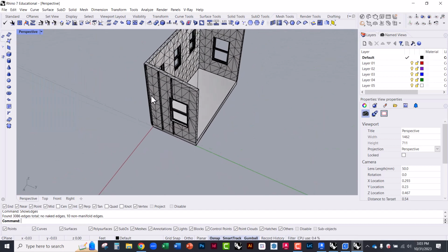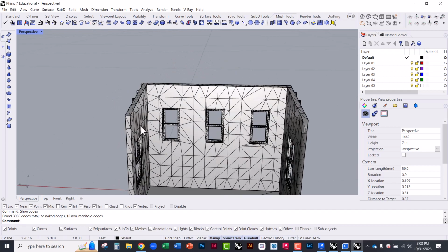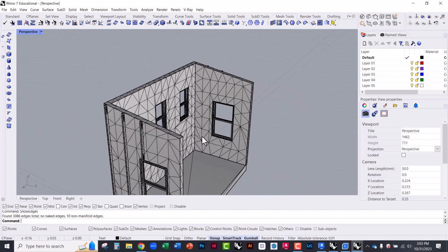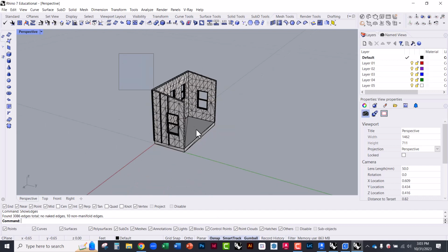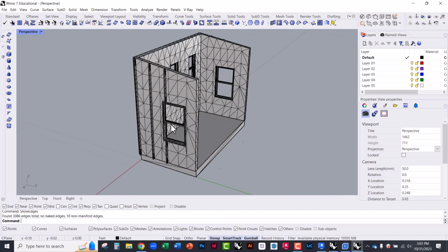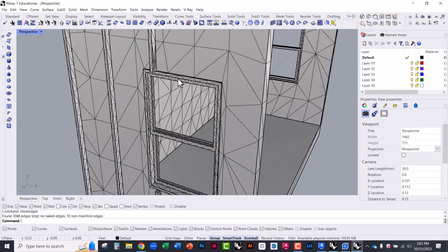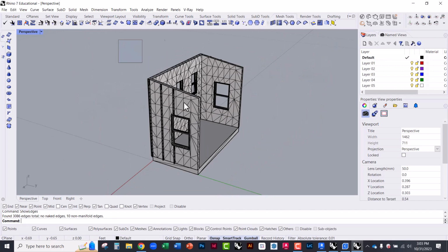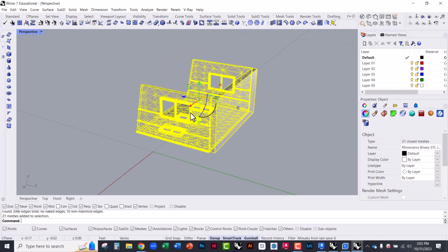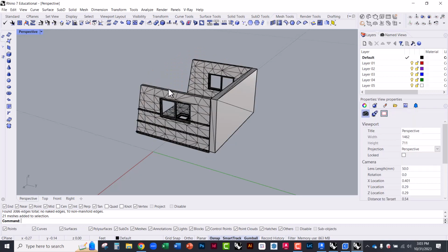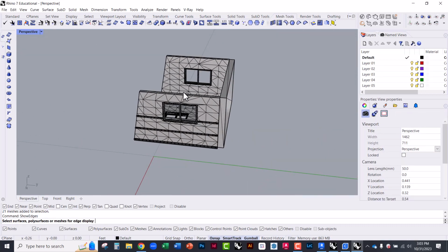And since this is kind of down to its bare bones, it really won't require much support material. If I print it in this orientation, it won't require supports. Maybe, yeah, actually it'll put some support material in this window that I can then break away later on. Imagine if this model were oriented this way, right? It still wouldn't require supports.